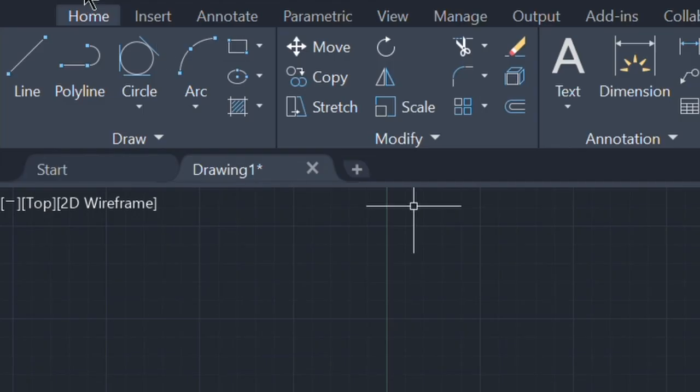It requires your center and your radius or diameter. But in this case, since it is only part of a circle, it also specifies a first point and a second point. So how can you do the arc command? You just look at the ribbon tab and there you have an arc. Click arc, and by default, the arc you make is just 3 points. So specify first point, specify second point, and specify third point.